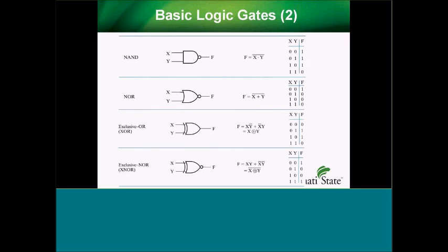They frequently have a hard time understanding NAND and NOR, but I tell them you just separate out the dot. The dot is what does the inverting. It's just an AND gate, and then you just invert the output. So this is just not AND. That's all it is. It's just the inverse of the AND function. The NOR is just the inverse of the OR function. I tell them initially that these are the two most important gates in digital electronics. And later on, I go on to tell them that you can make everything out of these. Then we talk about the XOR and XNOR.